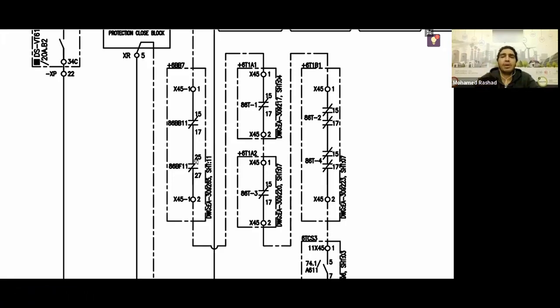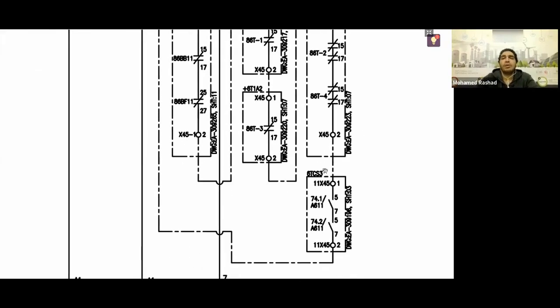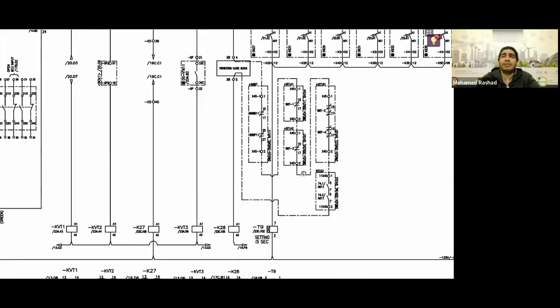In the end, all of them are lockouts, all are normally closed contacts. So if any of them operates, it will result in disconnecting your transformer. Therefore, the transformer here should open to prevent the breaker from reconnecting until a person comes to the station and sends a signal. All right, great. So we understand that the protection must be reset.